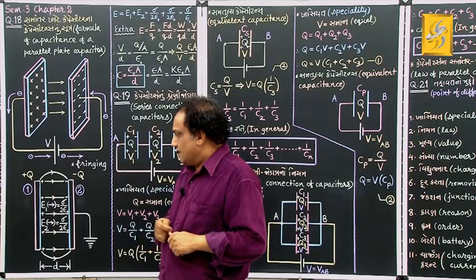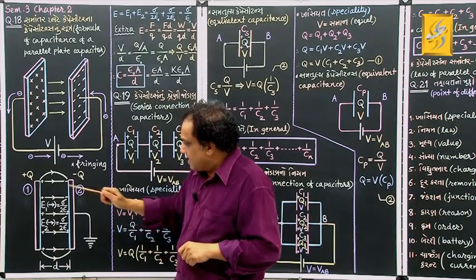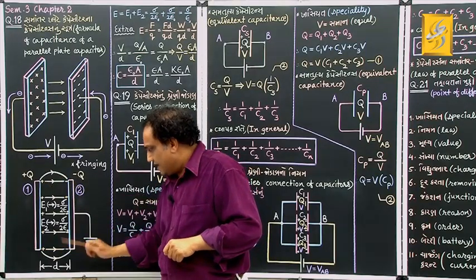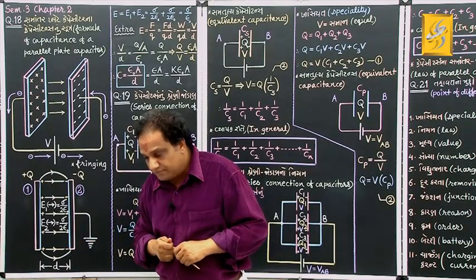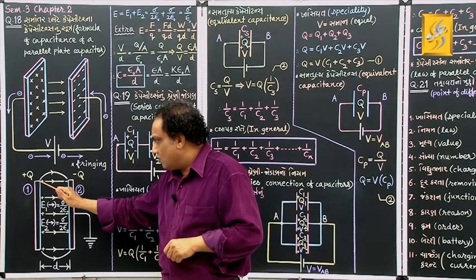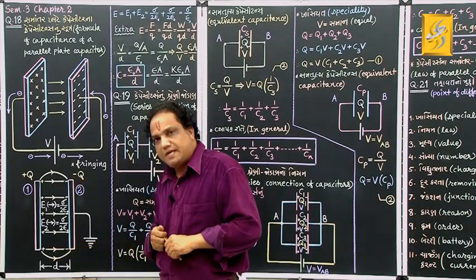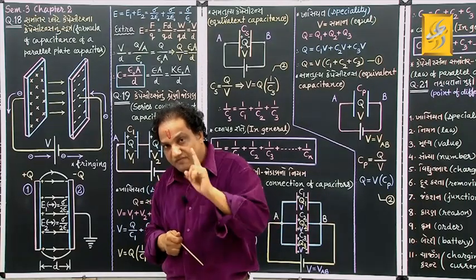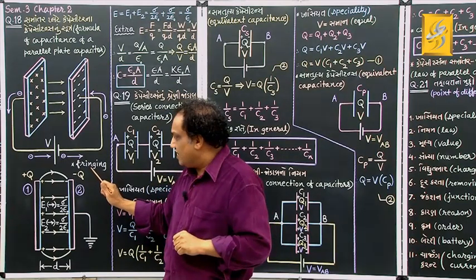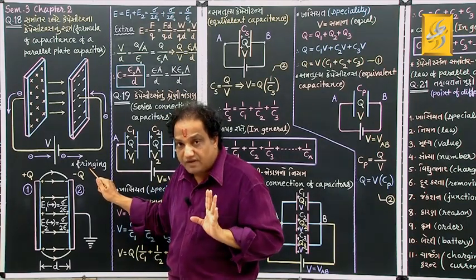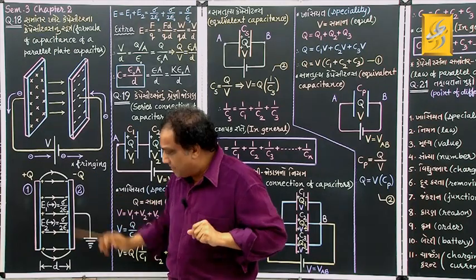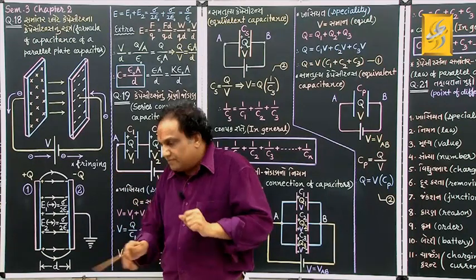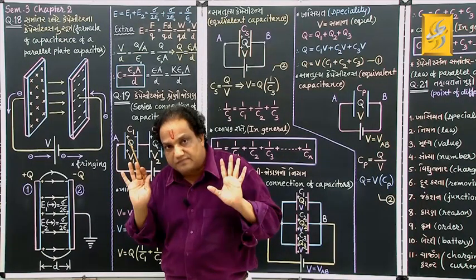Fine. Here actually what happens, at the edge of the plate, electric field is not uniform. That's why I am showing here curved field lines, correct? And that very phenomenon, having non-uniform electric field, in physics is called fringing of electric field, just for your kind knowledge, okay? If you keep the distance between these two plates very small, then this fringing can be neglected, okay?